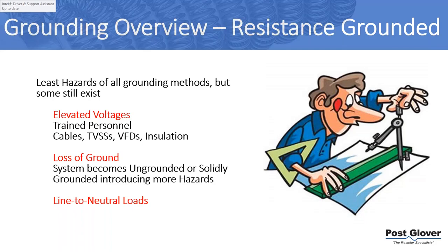Loss of ground. Essentially, you have a resistor that is typically alarming, and there's no tripping. It's not required to have a ground fault breaker and to actually trip in any situation in a high resistance ground system, since it'll never go higher than 5 amps. Some engineers like to have it anyway and set it up for a potential short on the resistor or something like that, which is fine. That's something you can do, but essentially you don't need to, and you're just alarming.